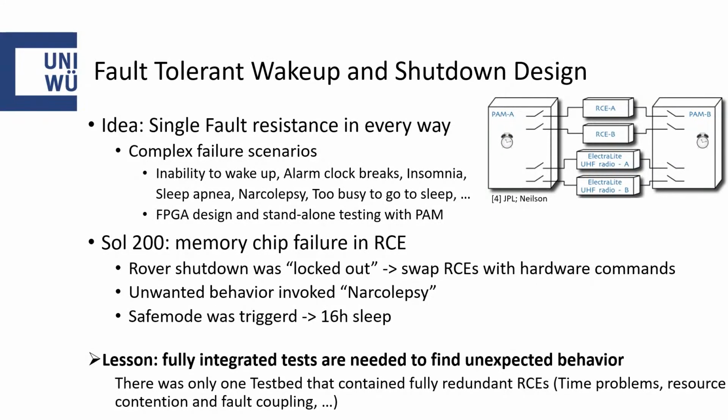The PAMs are programmed to turn it back on within a minute. If the RCE switch is permanently broken, the PAM will turn on the other RCE, and if there is a problem with the prime PAM, the backup PAM will turn on the backup RCE using the backup switches. So the newly prime RCE will then initiate a safe mode following this type of failure to save the whole system and go to sleep. So you see there's a redundant system and overwatch function of each system over the other system, and therefore it should not fail.